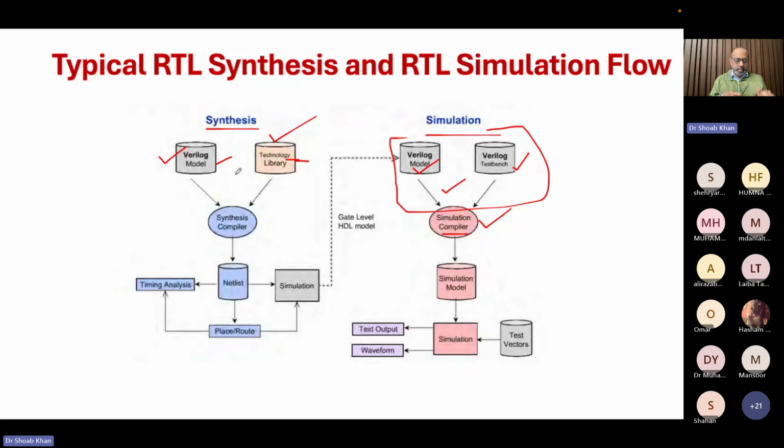Precisely the same case is for hardware: once you have Verilog code, you need to say how it should be converted into low level gate level primitives. For example, there may be a 3 input AND gate or 4 input AND gate in the library, and so the translator would know that this is all that is available.